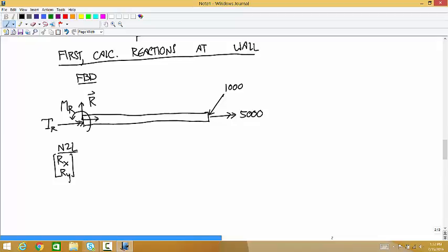And we're going to calculate the loads applied to the half that we're isolating by the adjacent parts of the beam, and that's going to be the internal load. But they are related to that, it's in the same ballpark as what you're talking about. We're going to end up calculating a horizontal force component that's equal to the tension, a vertical force component equal to the shear force, and yeah.